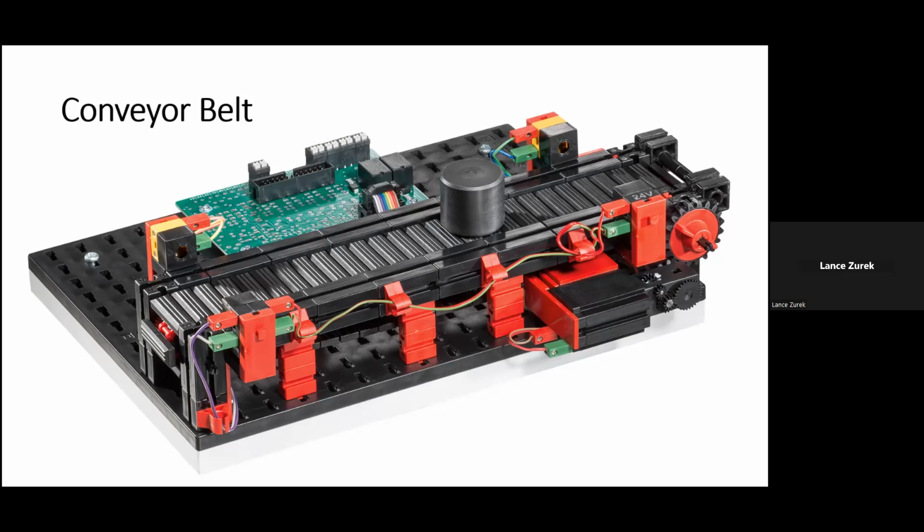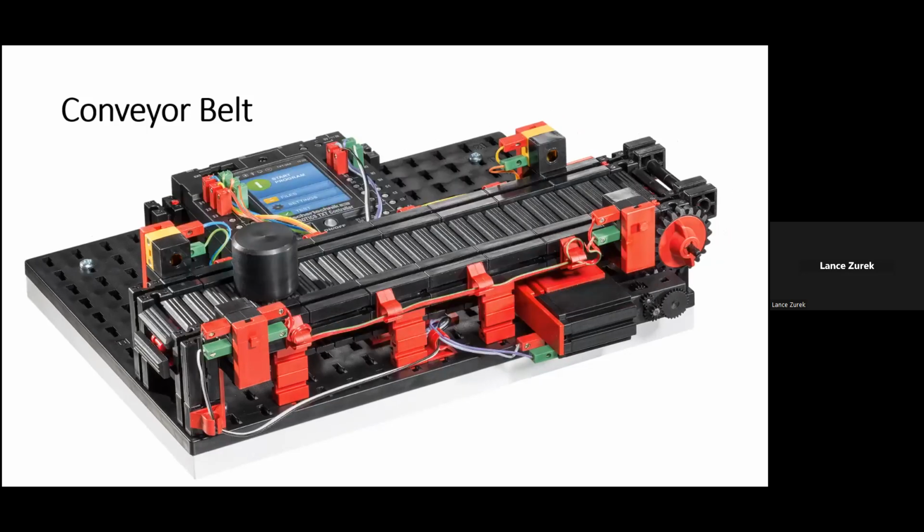Components on this model include an XS motor, a push-button limit switch, 2 photo transistors, and 2 LED light barriers. Dimensions of the model are approximately 14 by 10 by 4 inches, and it has a weight of just under 2 pounds. And as before, the standard 24-volt variation does include a multi-pin connector, but in this case, it's a little bit different. It's a 26-pin connector with a 2.54 millimeter grid, as shown in this photo. And for a limited time, we do also offer 9-volt versions pre-wired to the robotics TXT controller, as shown here. In this case, one 120-volt power adapter is required for operation.